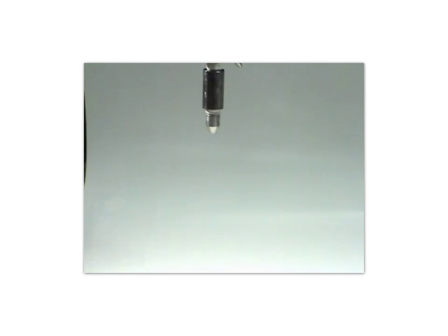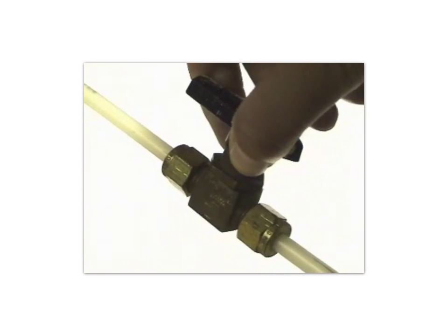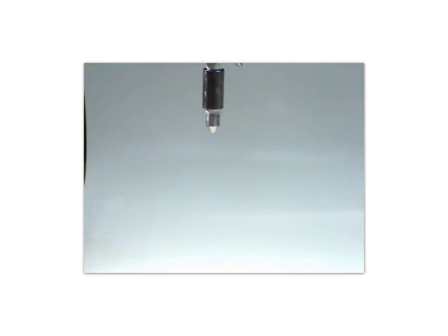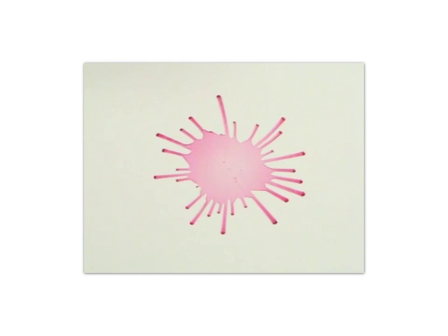One of the simplest of flow visualization techniques involves the motion of an oil film on a surface. Here's a compressed air nozzle aimed perpendicular to a flat white surface. This flow is invisible without the assistance of a flow visualization technique. By placing droplets of colored oil on the surface, we can observe streaking caused by the shear stress of the impinging air jet. This is a simple example of the oil flow technique, a method of surface flow visualization.